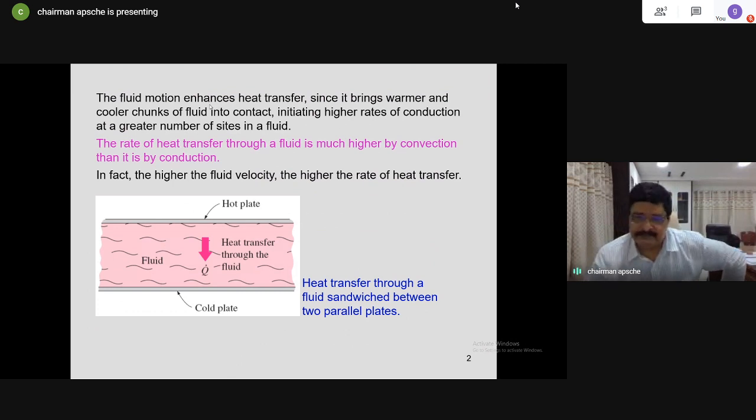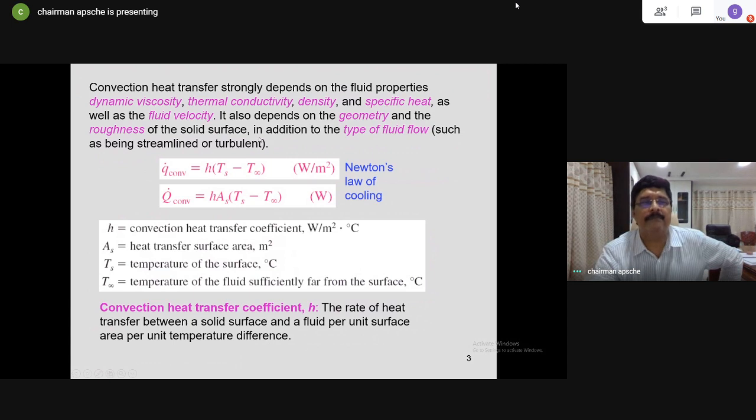Heat transfer between two parallel fluids is the case that is given here. So, Newton's law of cooling, I need not talk to you. Here, once again, I talk about heat flux and heat transfer. Heat flux is per unit area. A is missing here in this equation, and A is taken to the other side. Capital Q becomes small q, because small q is capital Q by area.